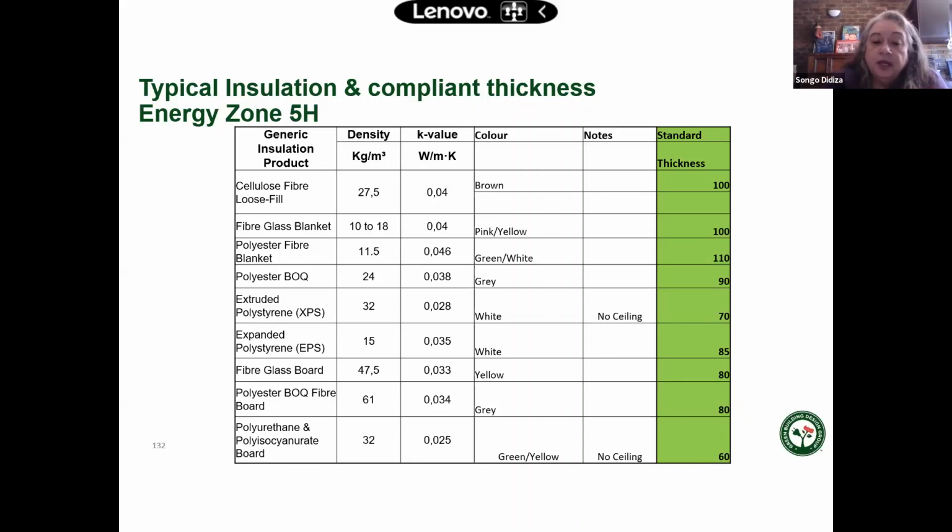What happens with the boards, the polystyrenes and polyurethanes and isocyanurates, is they've got what they call blowing agents. A polystyrene comes in little polystyrene beads. They're normally filled with a pentane. And as you add heat, they blow up into this board. And so they don't trap air, they trap these other things.